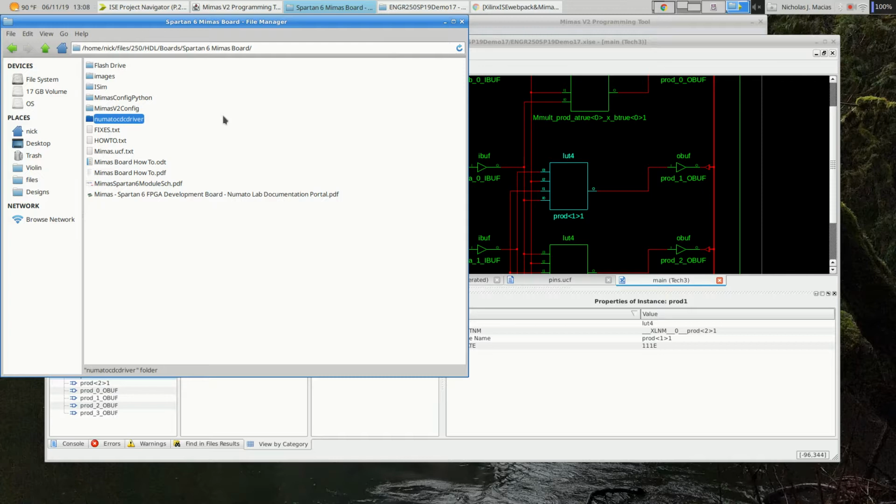It's not uncommon to find FPGAs that have microprocessors on board, though. Some of the stuff we do in 270 you might be able to do on part of one of these chips, or as I said last time, you can actually get Verilog for a whole CPU and dump that into your chip and build yourself a little standalone microprocessor inside that you write programs for, and you use that to interact with circuitry that you're building.